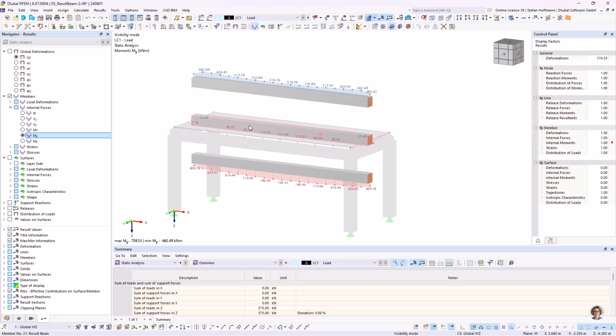Usually your task is to put the result beam into the centroid of the objects you would like to take care of. So the geometrical centroid. And if you do so, you can get a bending moment diagram which looks quite okay. It is related, of course, to whether you have line hinges at the start or not, because the beam is, once again, to put focus on just summing up inner forces of the surface or the objects it is taking care of. So the summed inner forces correspond with the stiffness of the model behind.